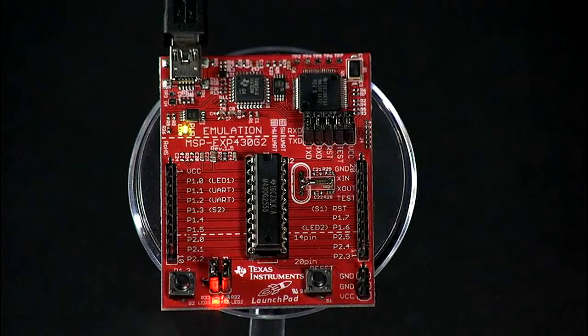The crystal was intentionally not pre-soldered on the board because these devices have a very low number of general purpose I/O pins available. This gives you, the user, more flexibility when it comes to functionality of the board directly out of the box. It should be noted that there are two 0 ohm resistors on the board, R28 and R29, that extend the crystal lead pins to the single inline breakout connector. In the case of oscillator signal distortion, which leads to a fault indication, those can be used to disconnect the J2 from the oscillating lines.